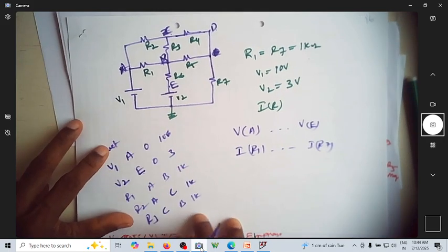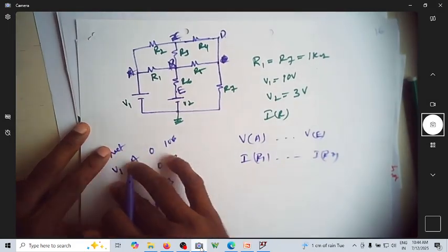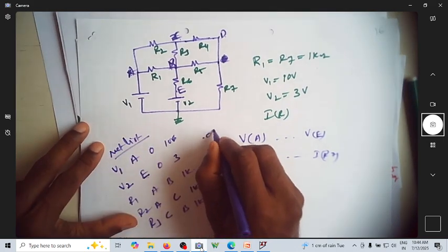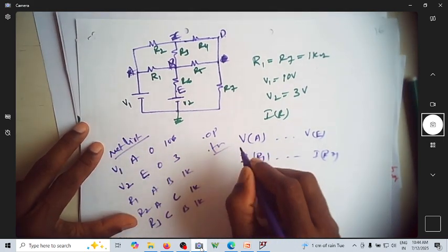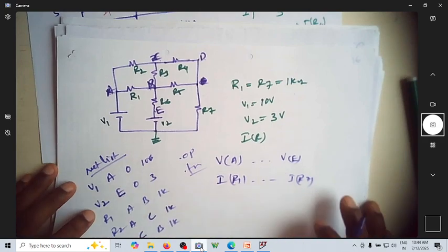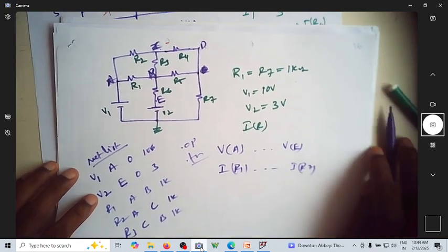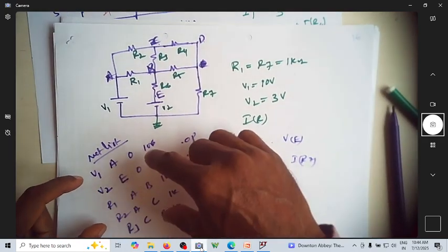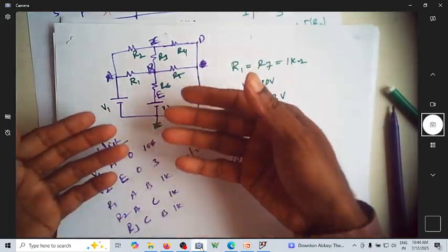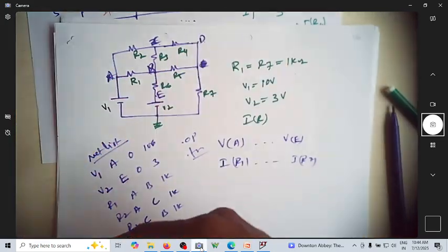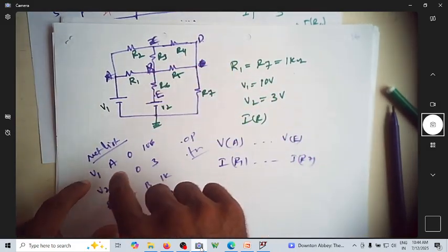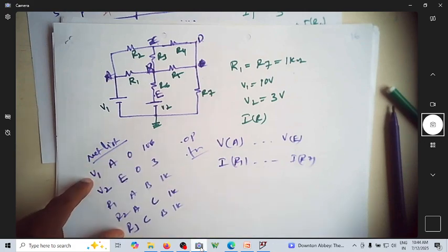Likewise, you just write it once, see it in your simulator, in your netlist program, do .op, do .tran. It's a fun exercise so that you know how to write a netlist program. Of course, you have a circuit diagram, and you're writing a netlist program for it, and this is what is generated for analysis in your LTspice.